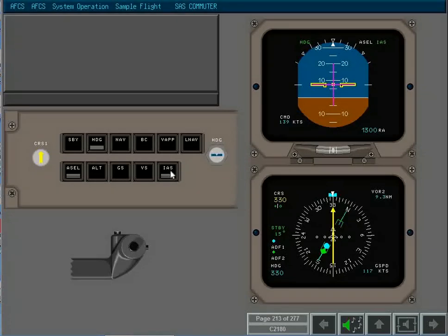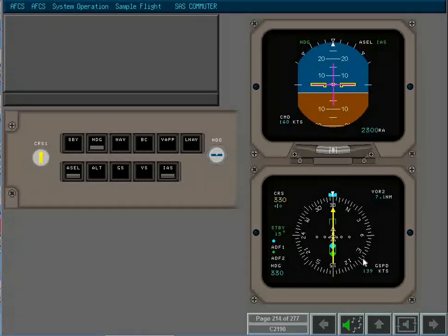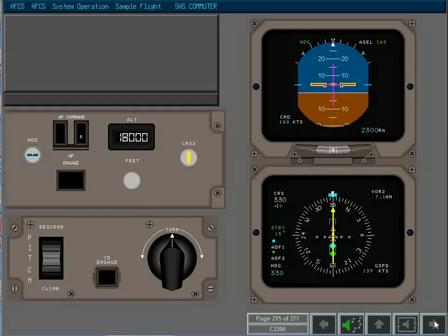Current airspeed is 139 knots. Use touch control steering to reset the pitch datum to command an IAS of 160 knots. Bringing the nose down has accelerated the aircraft to a speed hold at 160 knots. Normal climb is executed with a vertical speed of 1000 feet per minute and then a speed of 180 knots.